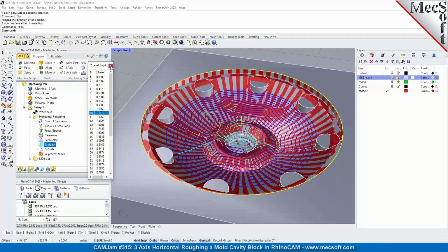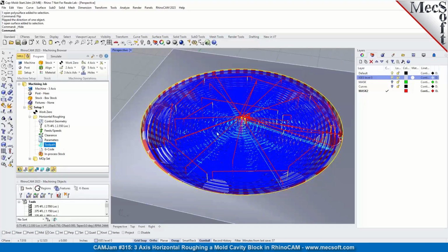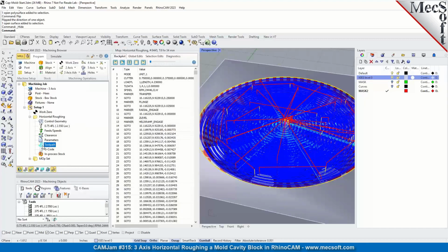Okay. And then another good thing to do is you can double left click on the toolpath icon, and it will, if I can get it, there it is. It'll display the toolpath viewer/editor. If you're in the standard configuration or below, Express or Standard, you'll only see the tool motions. You won't have any of these tabs up here.